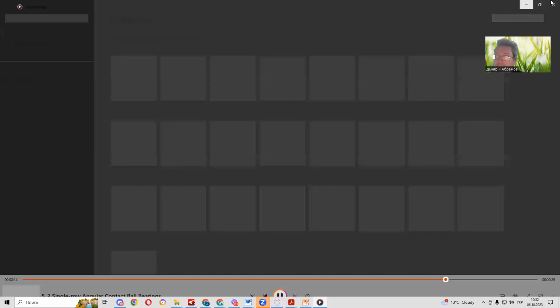We can see clearance fit if the tolerance field of the hole in the housing will be F, G, or H, fundamental deviation. H6, H7, H8. You can see the difference between these tolerance fields. If the IT grade is higher, the larger the tolerance field.